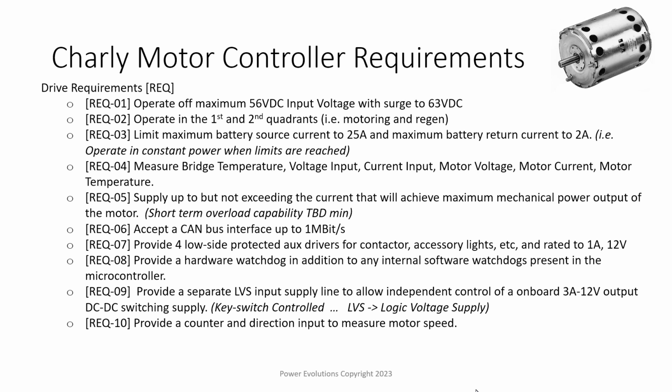Additionally, we need the controller to be able to output the current that will give maximum output mechanical power. That kind of gives you an upper limit as to how big your controller needs to be, or what sort of current rating your motor controller needs to have. And I'm arbitrarily choosing that point.